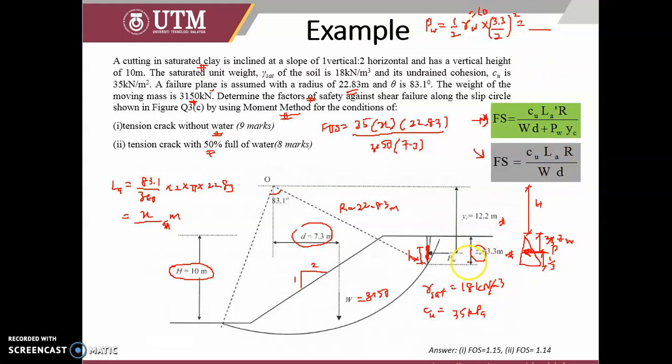So the pressure is below, so half. The sketching is not as big as this one. Let's say this is the height of ZW. So the pressure of water is only half of it, and 1/3 is only 1/3 from the half of ZW. So knowing that, you need to add 2/3 of half of ZW with the distance at the top from here to here.